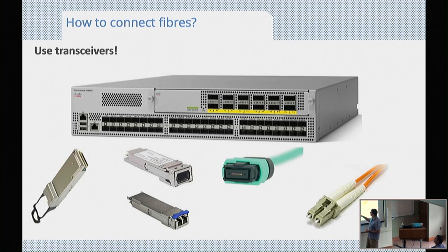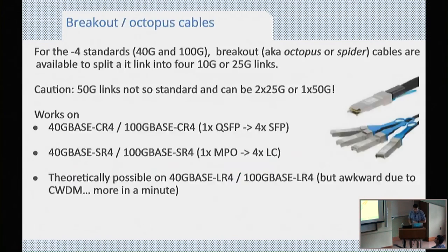And if you want to plug fiber in there, you get a transceiver. This is a transceiver for multi-mode that takes these MPO connectors. This is a transceiver for the LC type connectors for single mode, longer reach. And you also get these things called breakout or octopus cables.